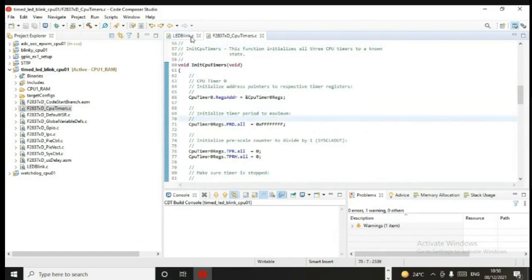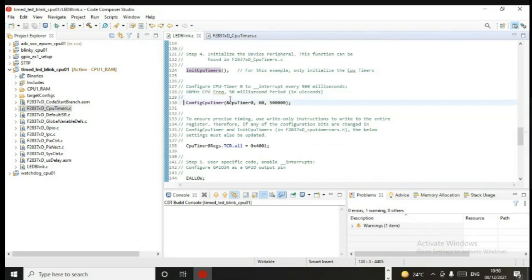So it is necessary that when you are using any interrupt which is triggered by your CPU timer, you need to initialize all the CPU timers. Generally, people use interrupts through EPWMs, ADCs, or CPU timers, or trip zone, whatever you want to use. CPU timers are a general way because the CPU works at a 200 megahertz clock frequency, which gives you the maximum clock frequency. So the time required to execute your ISR will be very little when you are using CPU timers as an interrupt, because you can operate up to 200 megahertz clock frequency as well.